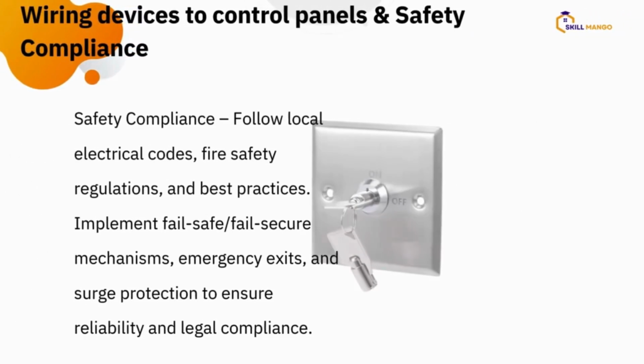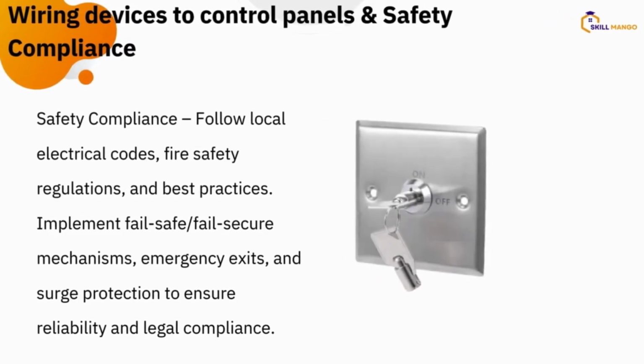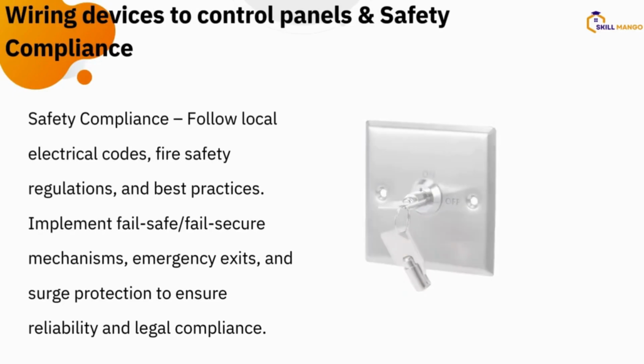Okay, so for safety compliance also, we usually advise that you follow all the safety compliance on the wiring. Ensure you use original quality wire. Wires should not be exposed, they should not be open. Any cable that is open should be well taped and well managed inside a box or inside the trunk, so it won't shock people. It will not touch each other. When the cables touch, because of the voltage passing through them, they can send the wrong signal or current to the system or even burn the system. So all these things have to be checked.